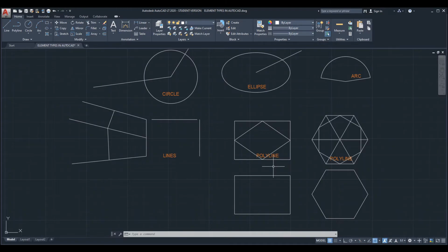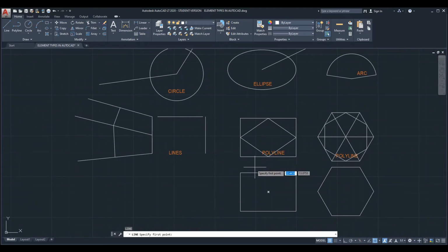So, let's click here on the line command. Okay, let me start it again. So start the line command again, and then here, if we touch the perimeter of this rectangle right here, we will also get the center, and then we can click from here, for example, and start to draw. Gonna click enter again, so we can draw something like this. And the same with the polygon.